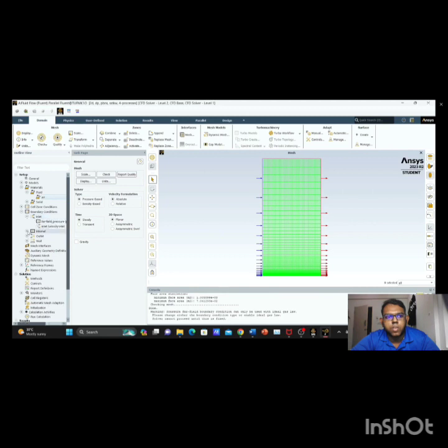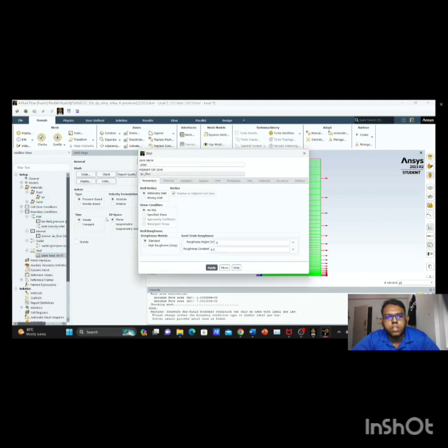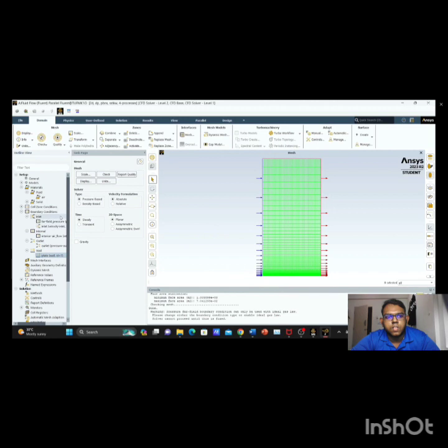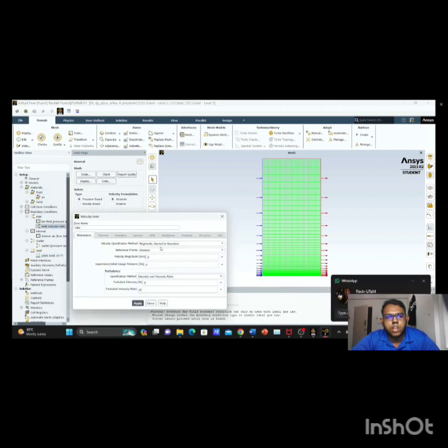Next up, we go to boundary condition. On plate, these are the settings. Just leave it as it is. Next, go to inlet. This is where we change our velocity magnitude. For our group is 1. Click on apply. Leave everything as it is.